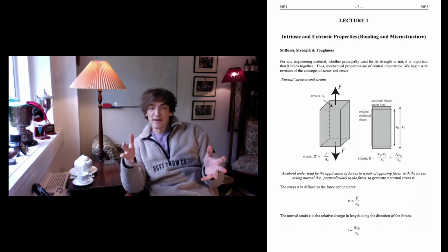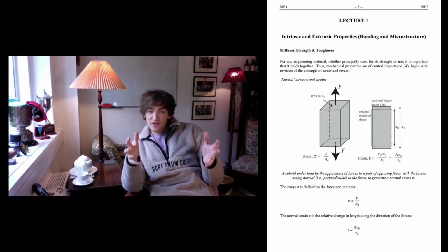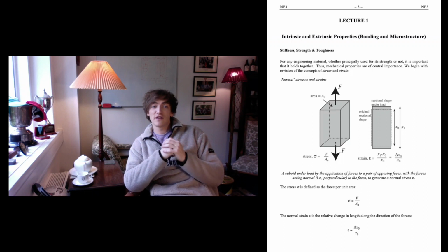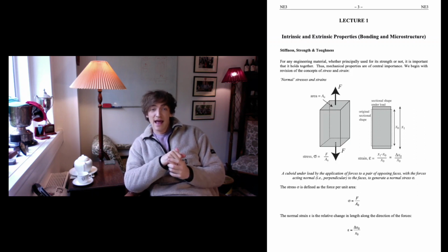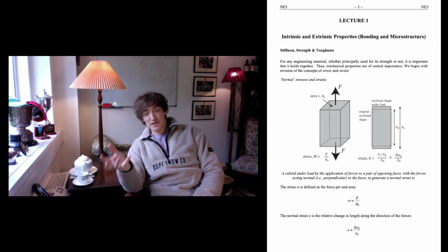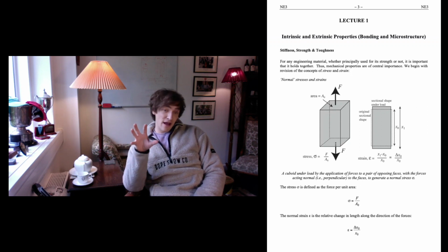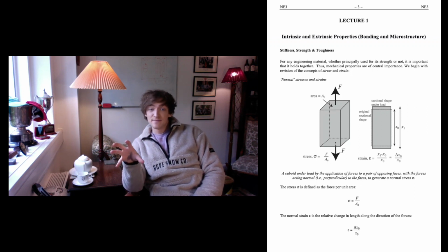But what about strain? Well, the normal strain is the relative change in length along the direction of the applied forces. And that is denoted by epsilon, i.e. epsilon equals the change in length over the original length. So these strains can cause deformation.